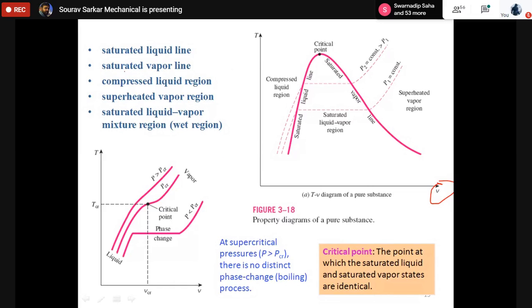This diagram is already given in your textbook. So I will simply take out this diagram. I will locate the temperature. It is 200 degrees Celsius. This is my 200 degree temperature line, and I will locate the volume. If it is intersecting somewhere there, I will call him back and say that you have a mixture. So simply, someone did these experiments and tabulated those graphs in a textbook. So simply knowing those values, you can identify what the state is.